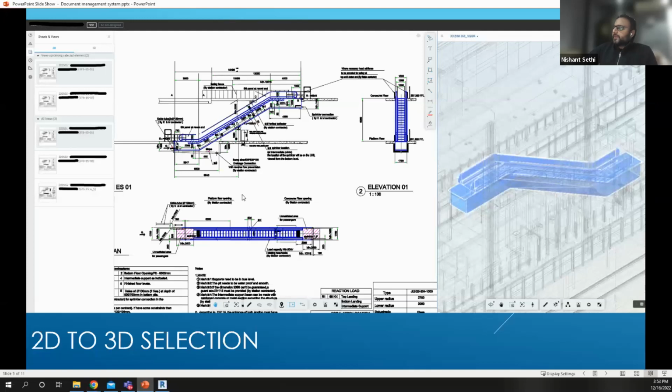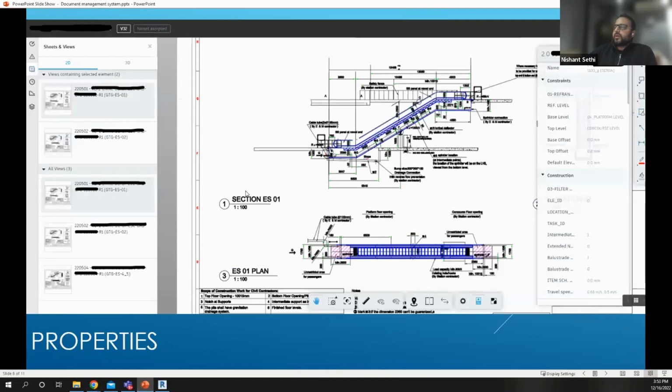So this was one of the aspects, the split view format in BIM 360. The other which I would cover, and Tushar also already covered, was the property palette in BIM 360. As everyone knows, most of the people here would know about the instance and type properties of an element, which get displayed in Revit. Once you click on a particular element, the properties you see on the left hand side are the instance properties, and edit type properties are called the type properties.